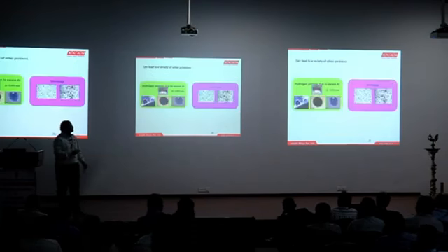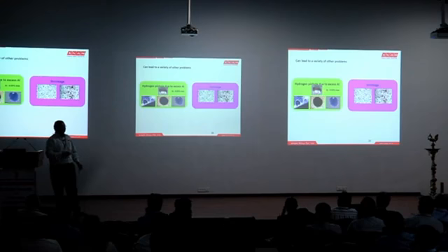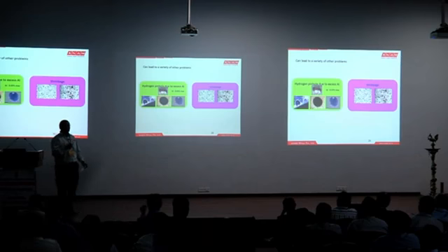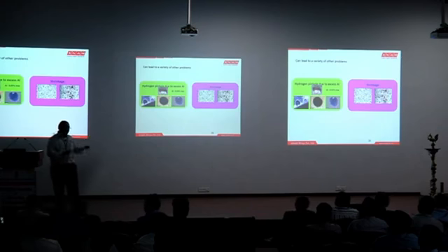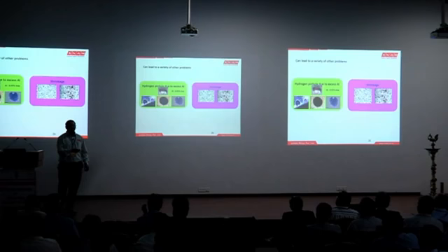Hydrogen pinhole tendency, aluminium. Actually aluminium, you can call it a catalyst. That does not mean increasing aluminium will give you pinholes. When you have surroundings with high moisture and a lot of gases coming from the mold and the liquid metal and less permeability, in that case when high aluminum is present, it can lead to a pinhole. We even have a variety of inoculant which contains 4%, 5% aluminum, which is successfully being used in manufacture of gray and ductile castings. So it is not that high aluminum, it is the environment around, and the presence of high aluminum can create pinholes, or I should say aggravate the severity of pinhole.